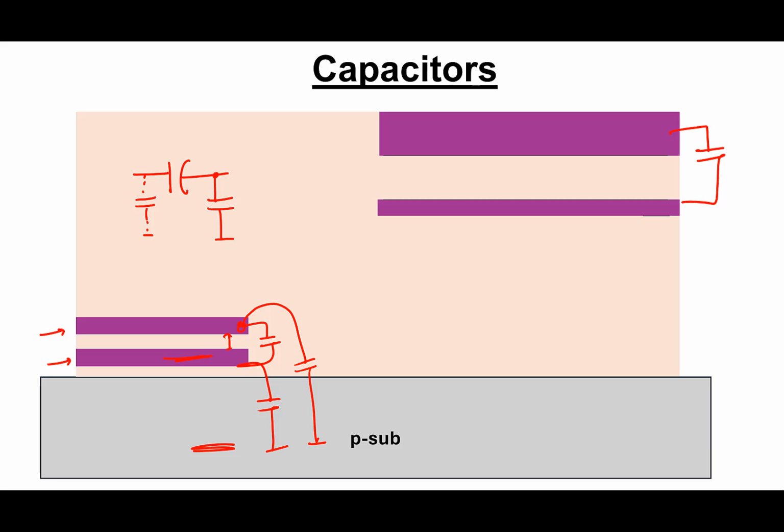So based on this, which is better? Top one, right? Because here it's going to be much smaller. Typically these kind of capacitors are called MIM capacitors, metal insulator metal, and these are made usually at the topmost metals. And sometimes you will find that two special metal layers are reserved for making capacitors alone. One metal layer can be just below the topmost metal, one just above it, and capacitance might be formed between these. Two separate metal layers might be reserved only for making capacitors, and not for connections. So usually it's done at the top. Okay.